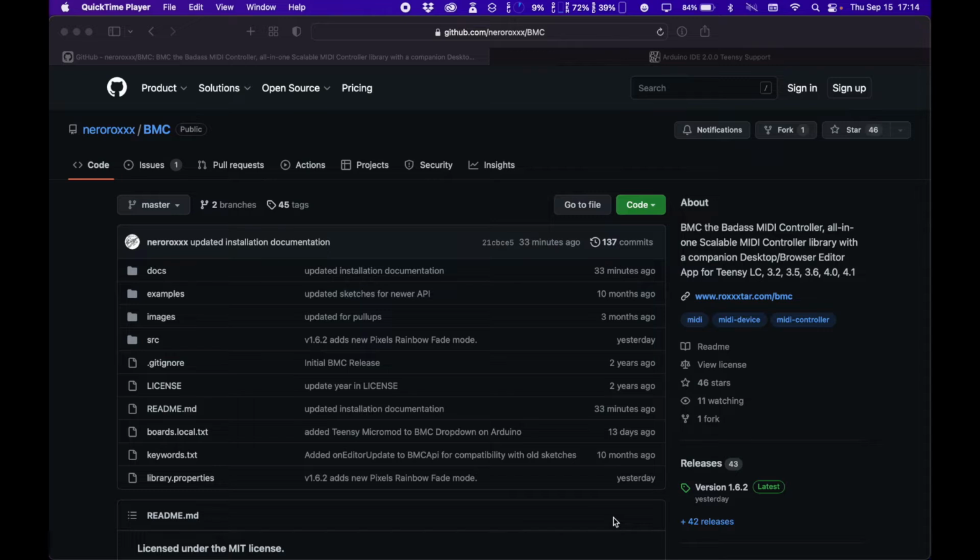There's already another video on my YouTube channel, but there's a much easier way to do this now. In the past you had to do a boards.txt modification to the Arduino IDE. Now you don't have to, now you just do it all by installing the library and installing a board from the boards manager. So I'm just going to show you the instructions on how to do this.